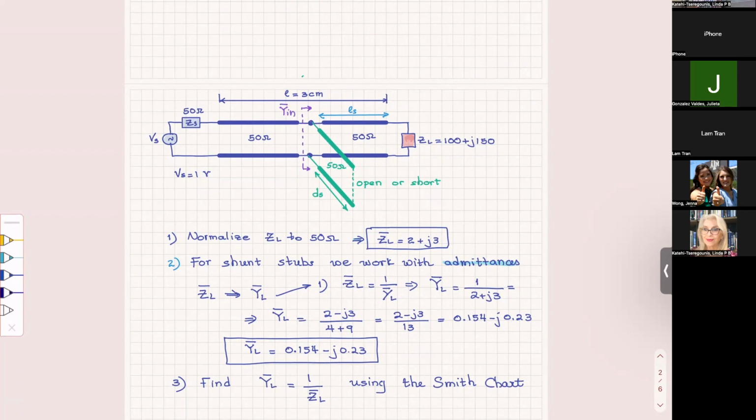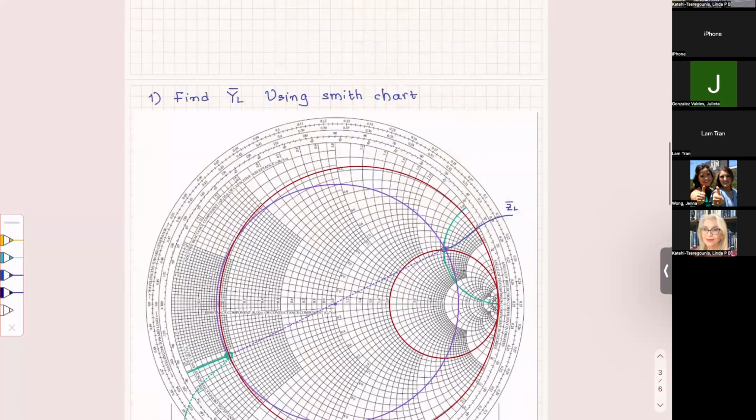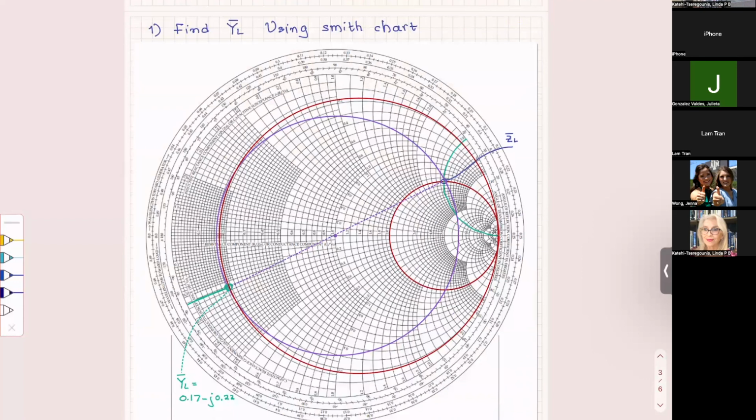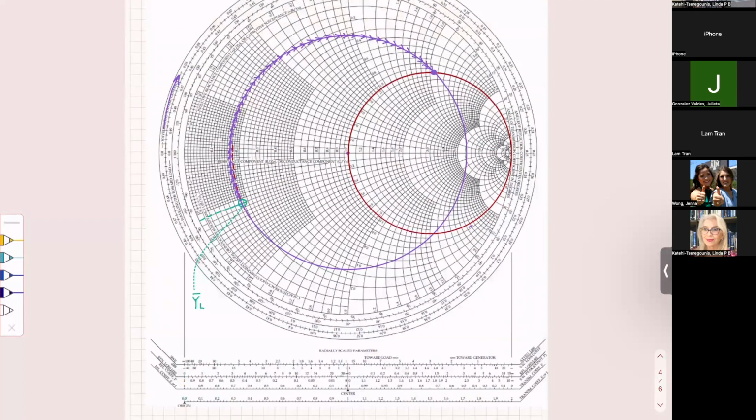The real part is gonna be equal to 1, normalized with respect to y naught. So we need to find the circle that has a normalized real part equal to 1. There are 2 points on this circle. So I can either go like this or extend to point A, or continue my journey and go to point B.